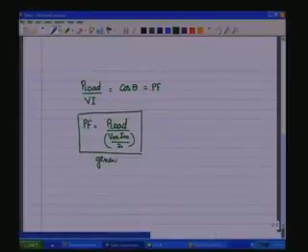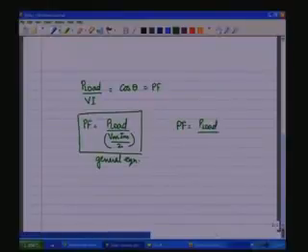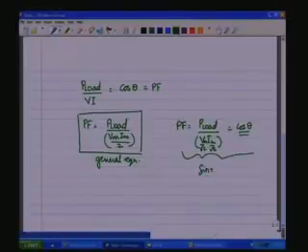Pf is equal to P load by V I, that is Vm by root 2 times Im by root 2, for the case of sinusoidal. This is equal to cos theta, the specific equation for sinusoids. So, the power factor for sinusoidal waveforms is cos theta. So, we stop at this point after our discussion of the power factor and continue in the next class.